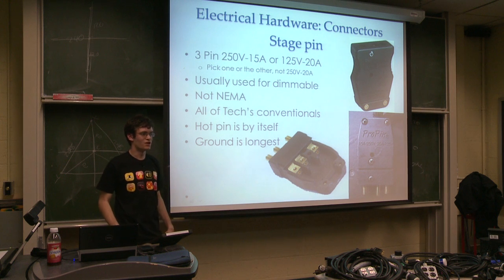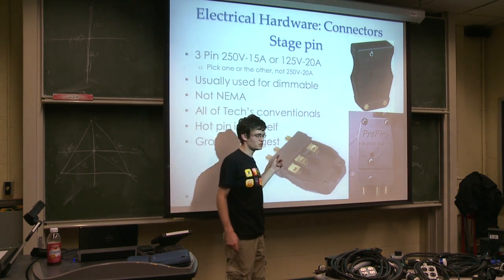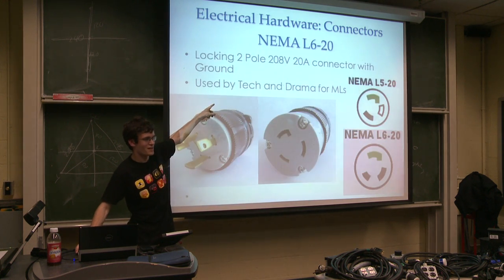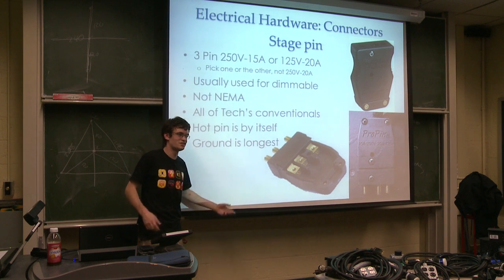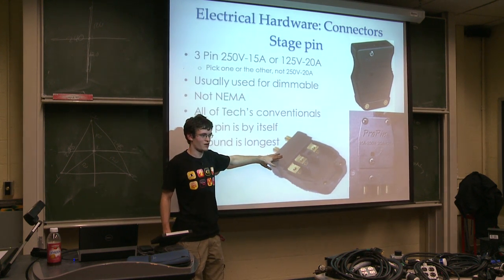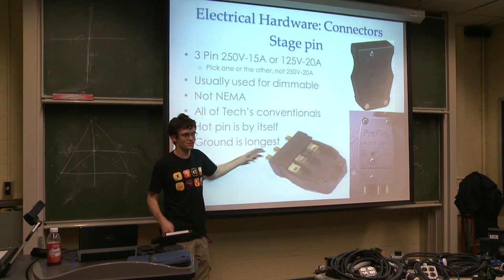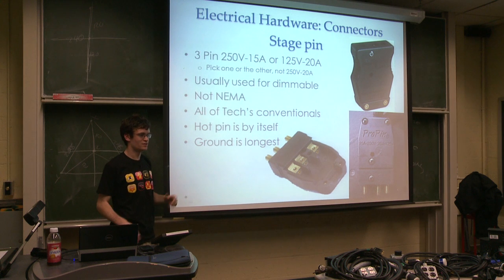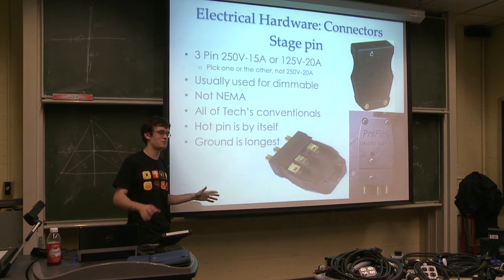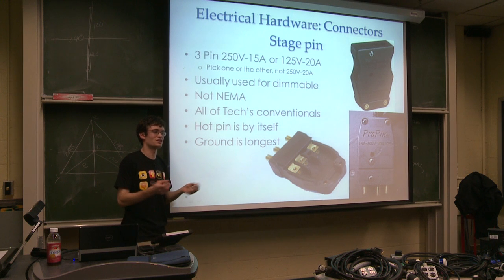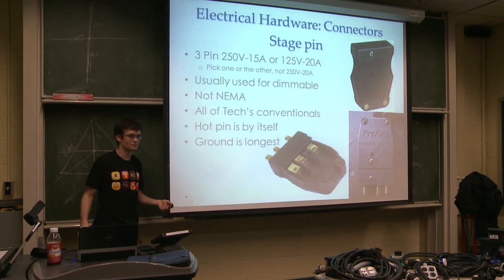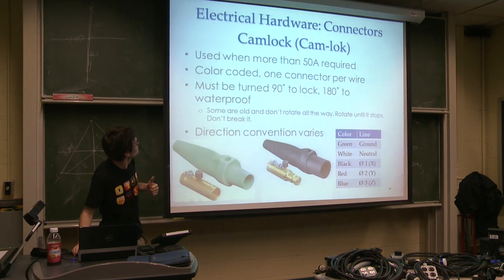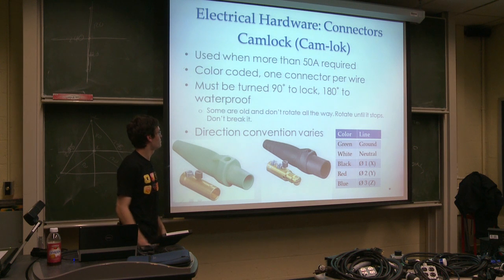Well, the wire can be, but often you use them for different things. If you know that there's some kind of convention that this is only used for dimmable power, you won't want to plug a computer into that, because computers don't like being on dimmable power. So it's a way of using different connectors for different things and keeping problems from happening, just by not plugging things into each other that shouldn't be together. And that's why we have different connectors in all these guys. Cool? Awesome.